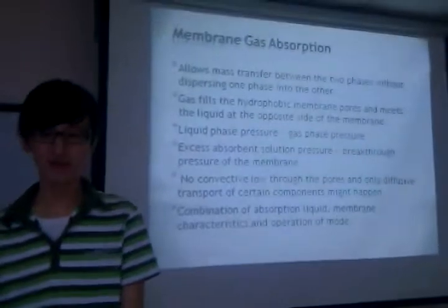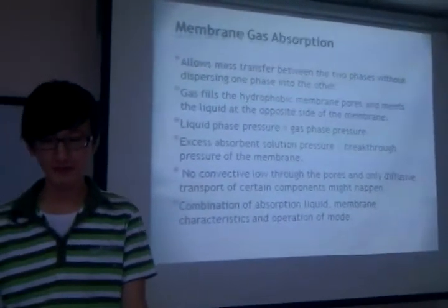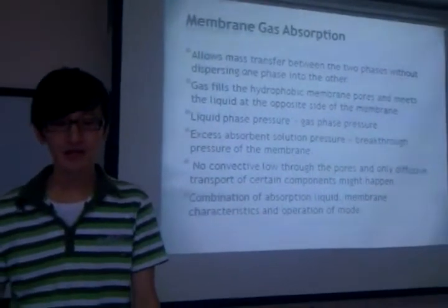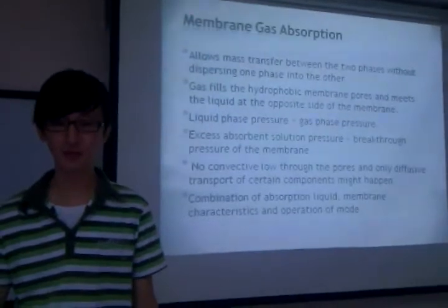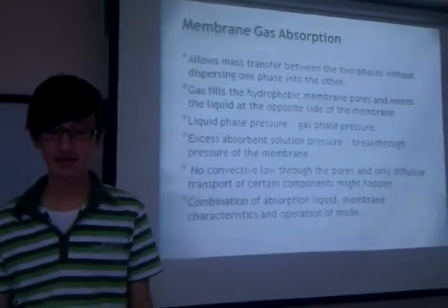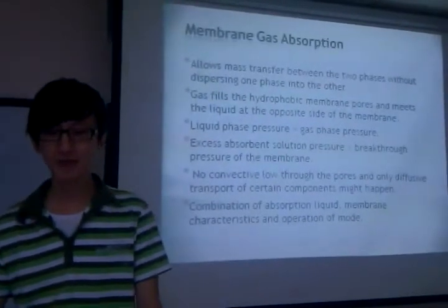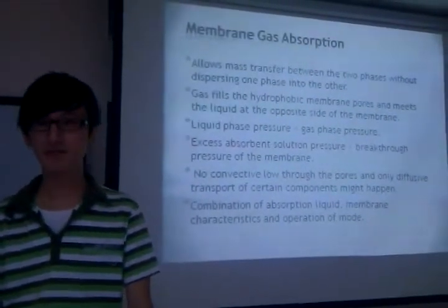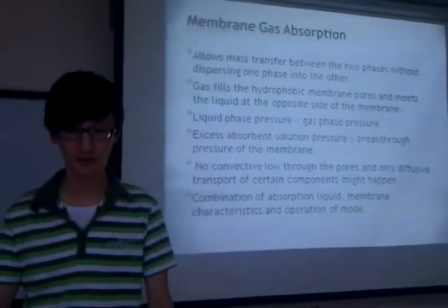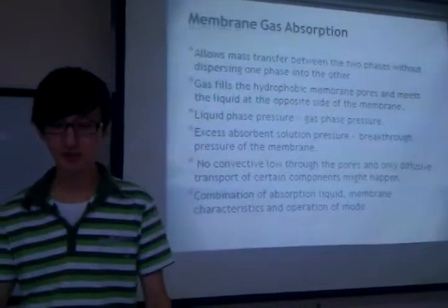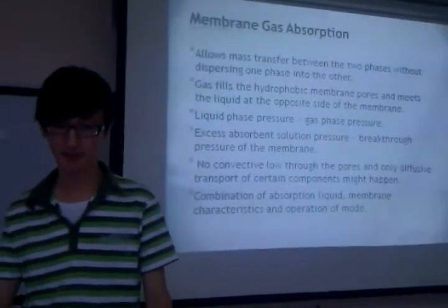Membrane gas absorption allows mass transfer between two phases without dispersing one phase into the other. The gas fills the hydrophobic membrane pore and meets the liquid at the opposite side of the membrane. Basically, the liquid phase pressure must be more than the gas phase pressure to prevent dispersion of gas bubbles into the liquid. The absorbent solution pressure must be less than the pass-through pressure of the membrane.